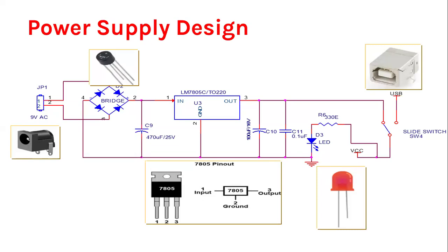An LED requires 3 to 3.5 volts, and for the safe zone every LED requires a current of 10 milliamperes. But the microcontroller gives 5 volts DC, and the current is 5 milliamperes for an output pin. If you use it as an input pin, it is capable of taking in 10 to 50 milliamperes of current. Please note this important point, guys.